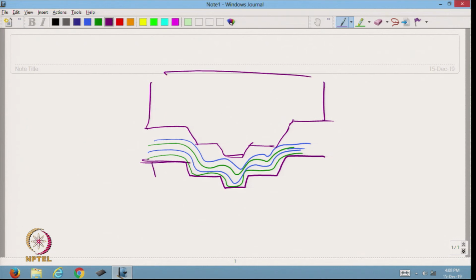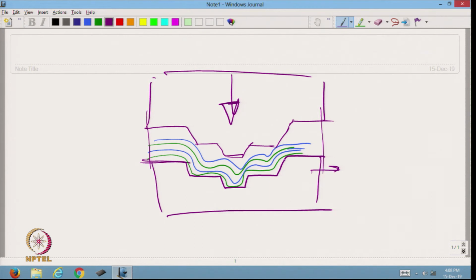Now, this is the base mold, and under high pressure this is pressed, and then the heater is on. These are the heaters, there will be heat. So, at high temperature the thermoplastic matrix melts and penetrates inside the reinforcement structure.